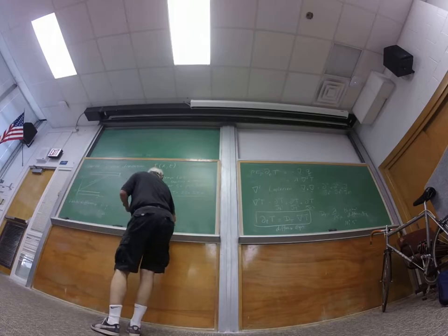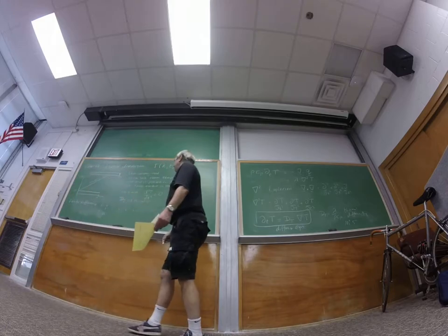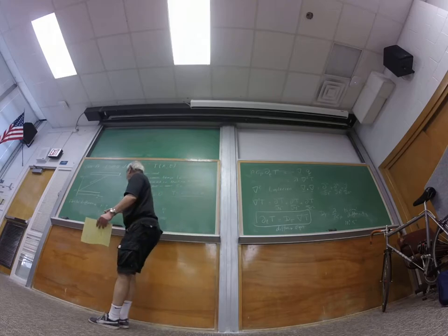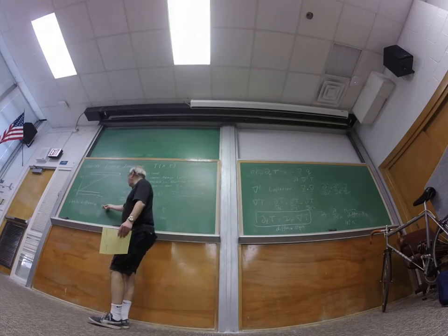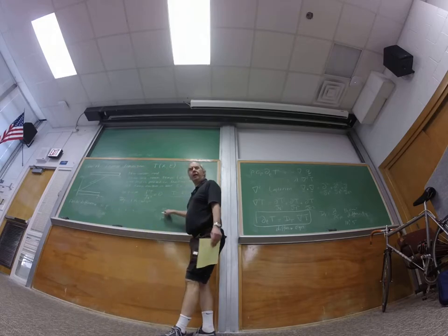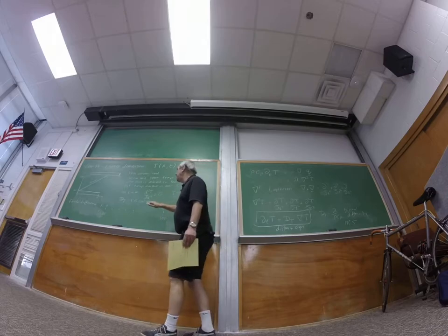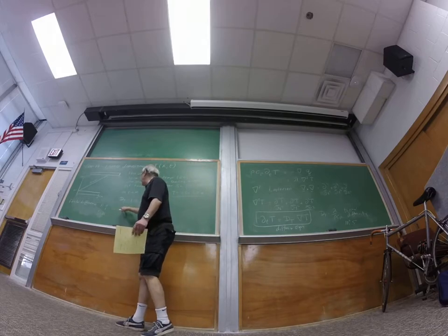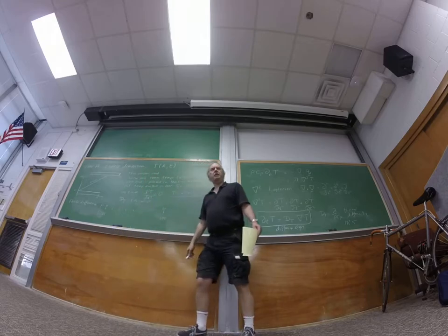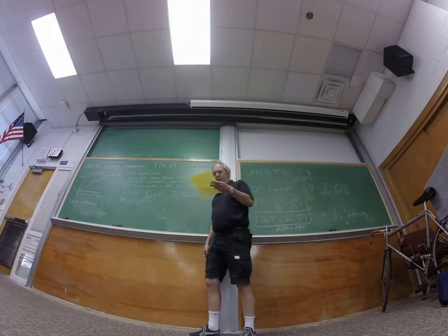And here we have T equals 100. And what we need, we know both of those things because the boundary conditions tell us that T is 25 at this end, and they tell us that T is 100 at the other end. But what they don't tell us, what we can't yet figure out, is what the temperature is at all those intermediate points. Okay, so that's what we want to try to find.